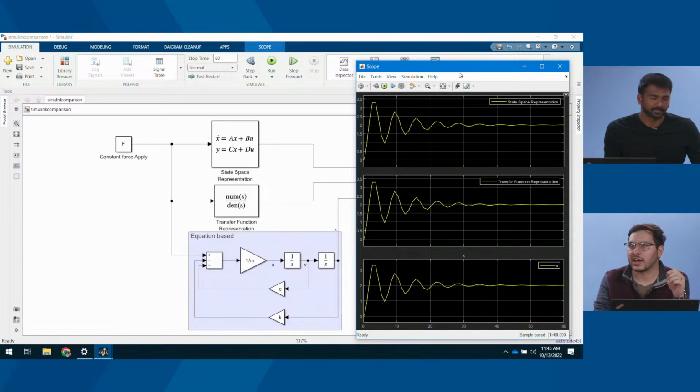And because I don't have any nonlinearities, I don't have anything that triggers at a specific time. There's not really much that can go wrong. But this is because I know exactly what this should look like. It's a mass spring damper. It's really highlighting why having my sample time be completely dependent on Simulink, you figure it out, is a problem. I've got some issues coming up. I want that data in between.